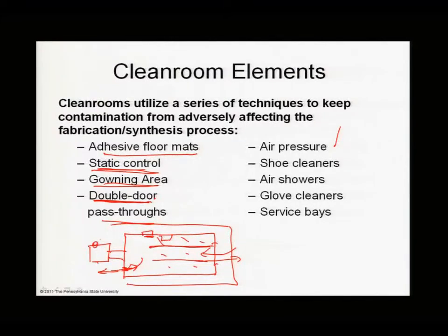Even though you have the shoes covered, you might want to make sure they're clean before a person puts something on their shoes. Often in clean rooms, folks actually change their shoes. There are special shoes just for the clean room. Then we have the air shower we discussed, glove cleaners, service bays. Service bays are also called, as we said, service chases.